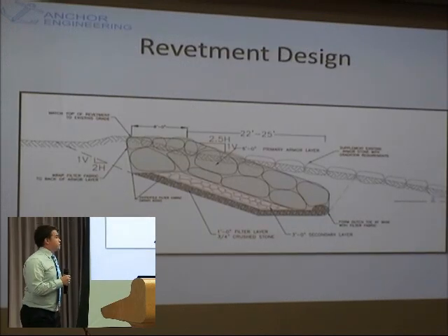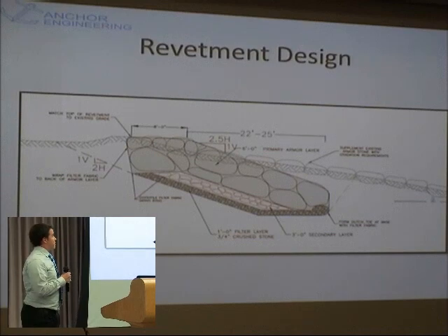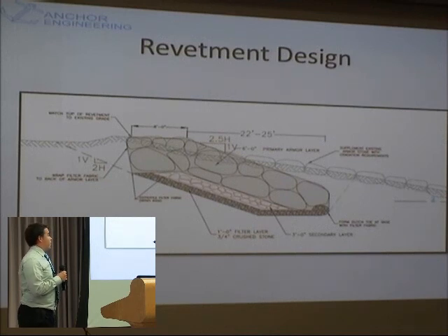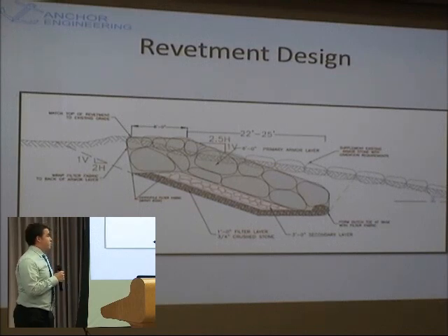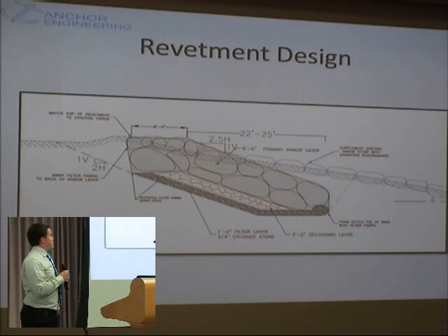Lastly, the second coastal feature that I worked on was the revetment design. I used Hudson's stability equation to come up with results for the design of the revetment. For the primary armor layer, I got a 6-foot thickness, and for the intermediate layer, we're using a 3-foot secondary layer, and underneath is going to be 1 foot of 3/4 inch crushed stone wrapped in a geotextile filter fabric.